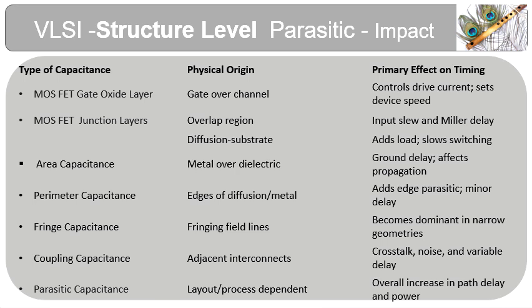At nanometer scales, these field interactions become dominant, affecting how charge and current flow in the circuit. The result is that every transistor or interconnect behaves as a distributed RLC network, rather than an ideal lumped element. High electric fields in short-channel devices introduce second-order effects such as velocity saturation and DIBL, further altering timing and current behavior.